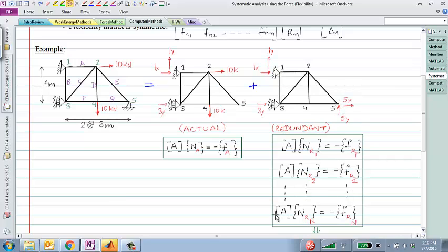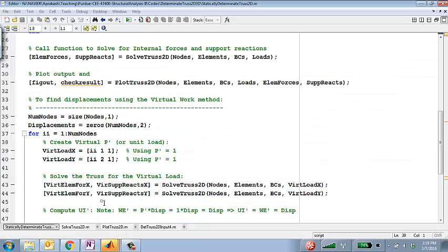So for each redundant point, we'll be solving a system of equations, which is not a big deal because this is just solving a statically determinate truss. Even in this case and even in this case, each one of those rows is solving a statically determinate truss. One call to our magic subroutine, right? One call to this function. That's what this is.